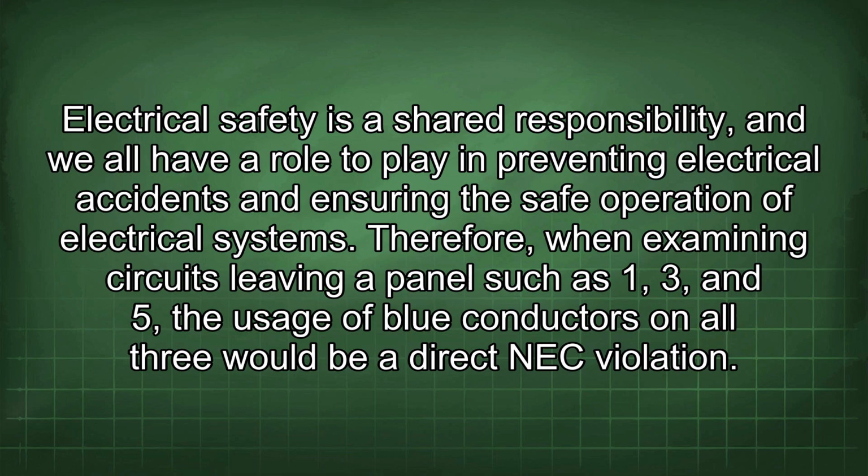Therefore, when examining circuits leaving a panel such as 1, 3, and 5, the usage of blue conductors on all three would be a direct NEC violation.